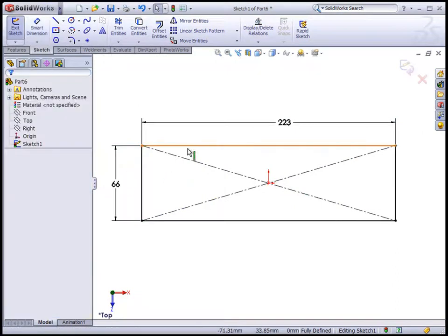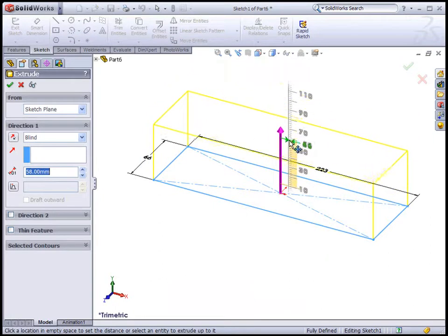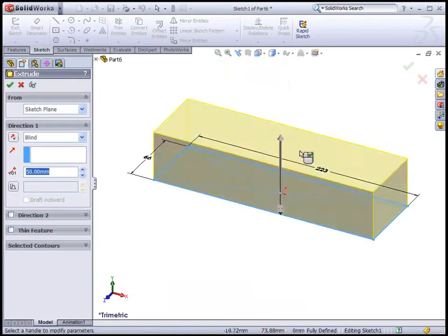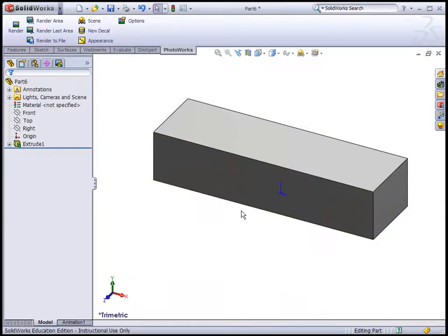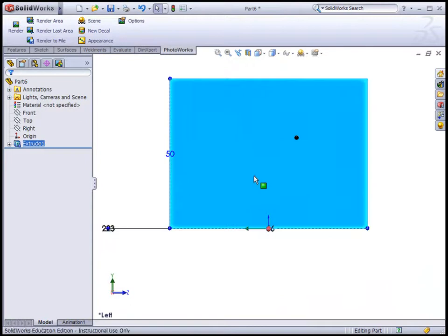Once this geometry is created, the user can then assign dimensions that will control the model, then transform it into a 3D solid by simply dragging it to the correct thickness. Using these same sketch tools, one can also remove material. Here, we'll create some cutouts in the back of our block.